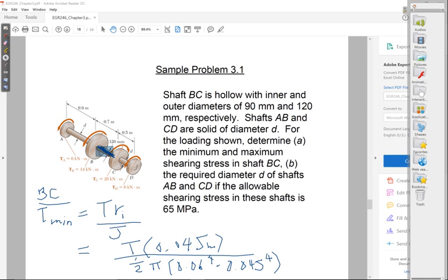And if you remember how we determined internal forces in those rods, you choose a reference, and then you make cuts and ask yourself what force you need at that cut to maintain equilibrium. Whatever that force is will be the internal force in that segment. So you do the same thing when it comes to torsion.